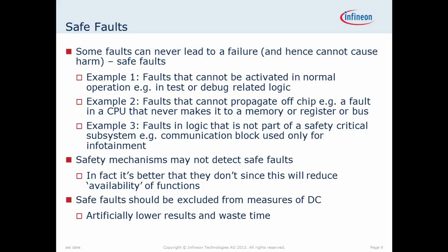Another example is you might have whole blocks of logic which are inherently safe. So you might have a communication block on your controller which is only used in the infotainment system. And if it's properly isolated from the rest of the controller, you can regard all the faults in that logic as safe.